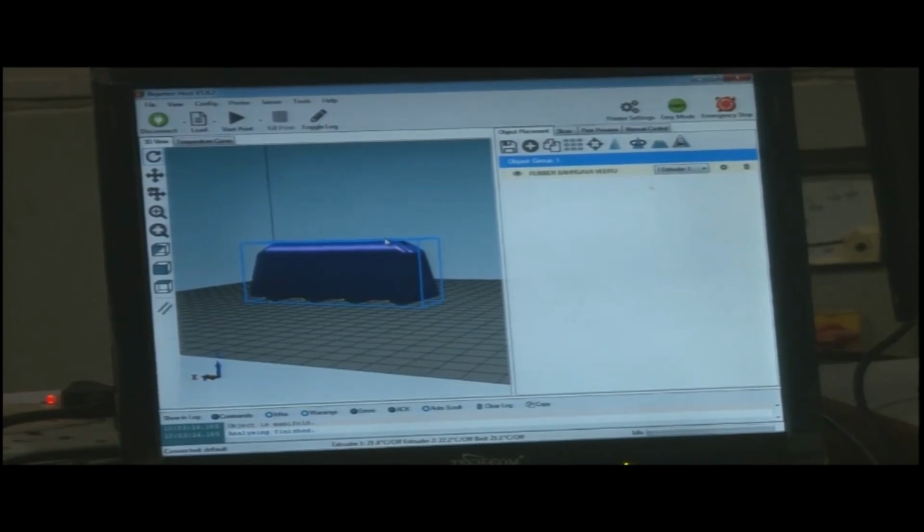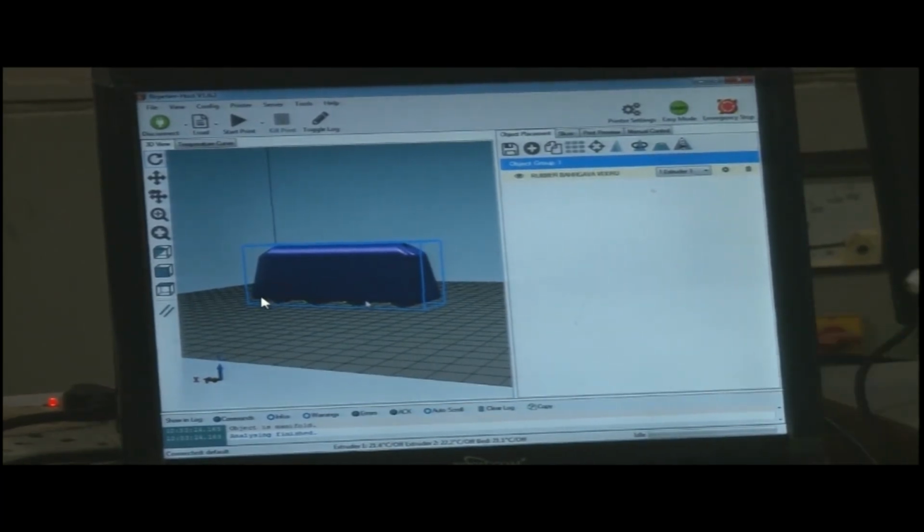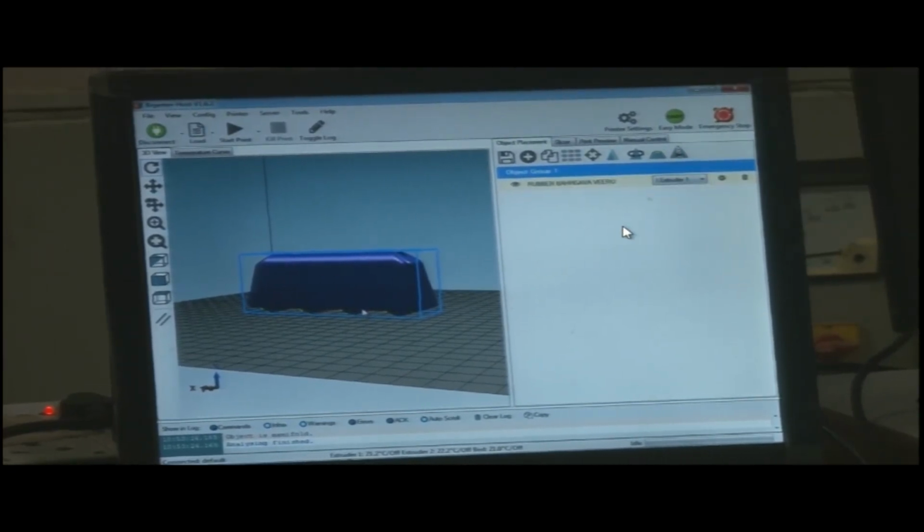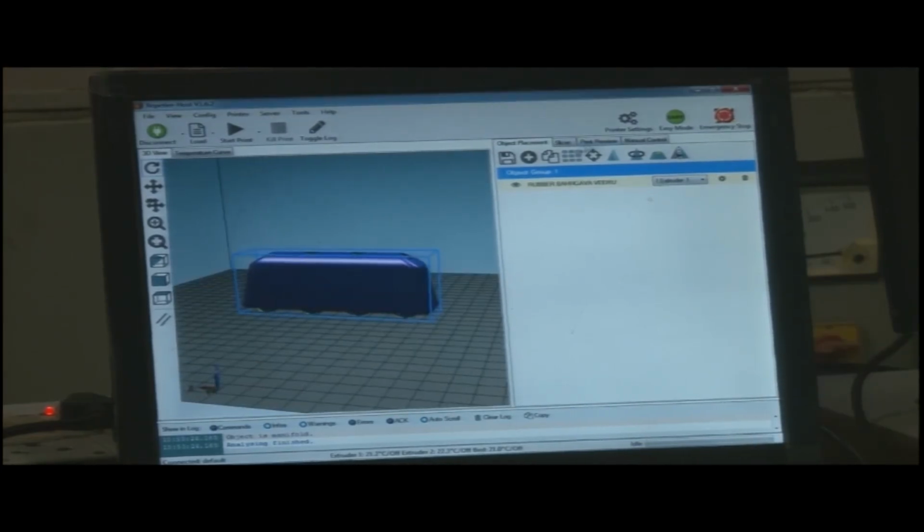The height of the entire job will be cut into a number of slices. How many layers there would be, the machine would just decide. So we have to program in terms of slicing, and the machine will deposit one slice in one stroke, and this will be deposited layer by layer and finally becomes a complete job.